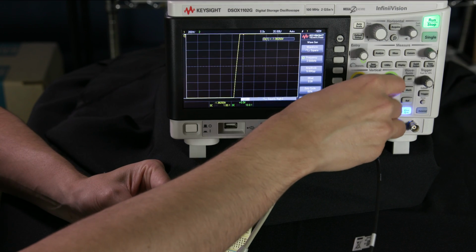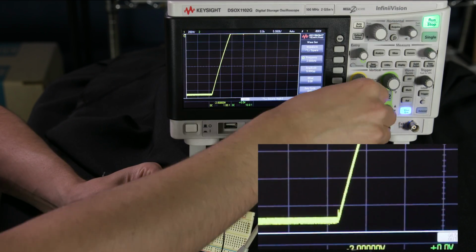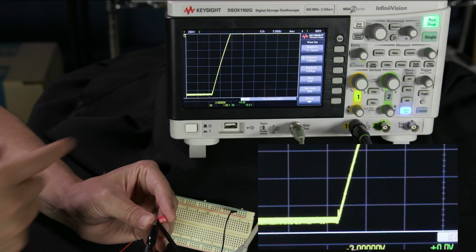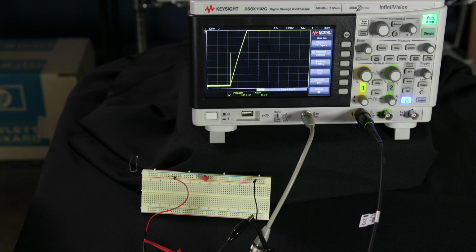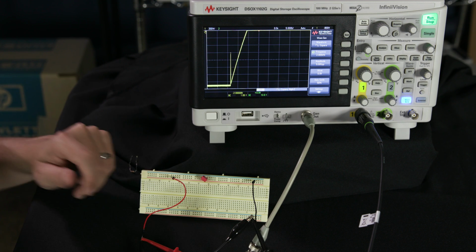I'm going to zoom in on that using my oscilloscope, and you can see if I look really, really closely, get really sensitive, there's a little spike there. But overall, my spike is gone because I've gotten rid of all the parasitic inductance. And you can see that spike is pretty good if I stay at that 200 millivolt per division setting and go back to my old setup.